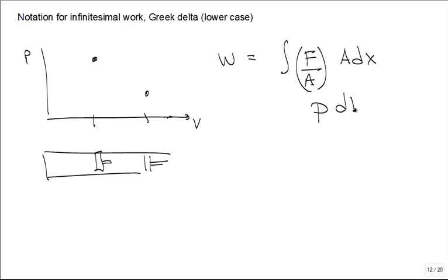Volume. So think about my piston face sweeping back; its area sweeps back dx. That's a change in volume. It swept the volume. So the work we can calculate by the integral of P dV. That's why we love these diagrams. So all I have to do now is go right here and calculate that work.